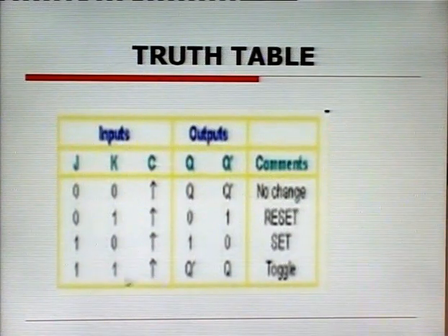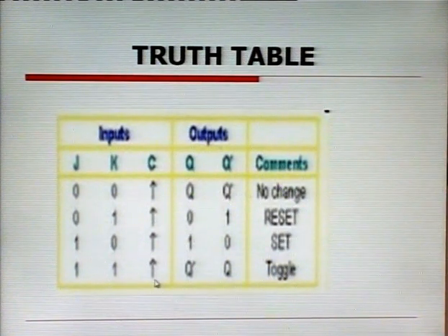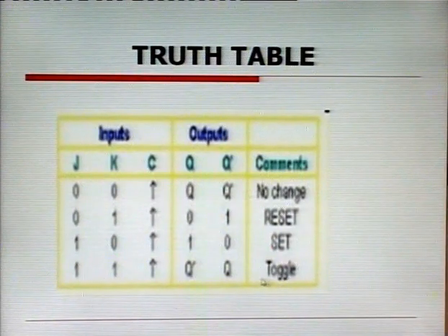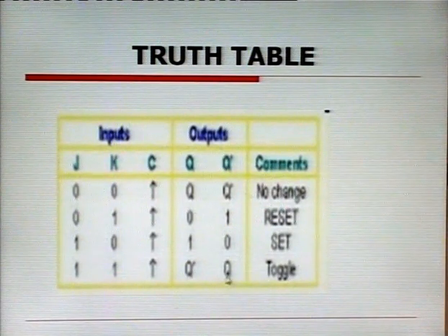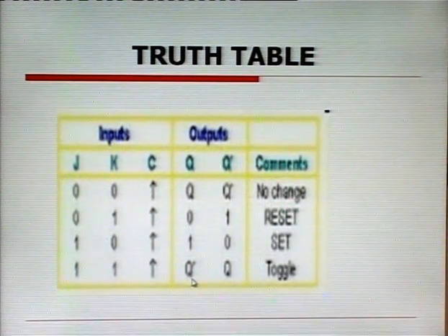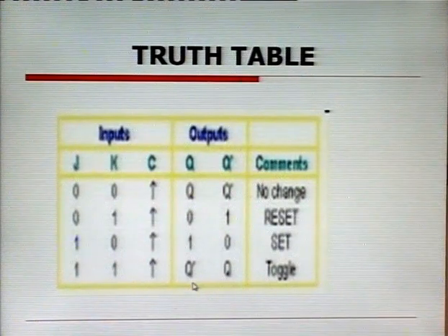And if both inputs remain 1 and there is the next clock pulse, in that case again the flip flop will toggle, that is, it changes its state. If it is previously set, it will become reset. If it is previously reset, now it will be set.